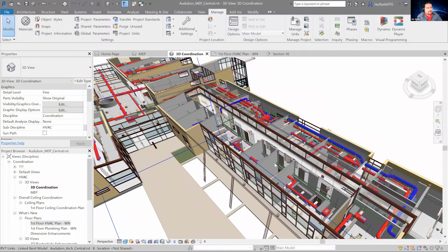Harold, thank you. Okay, from Sean. Sean, please explain the or option in the filters. Yeah, okay. When I'm creating a filter and I use and, it says the ducts, fittings, and the ducts, okay, and it has to have the system classification of return.